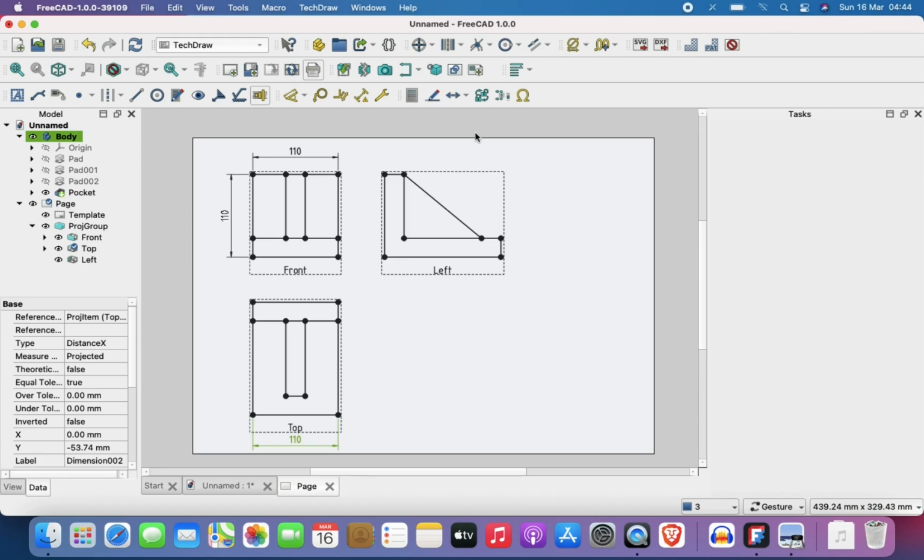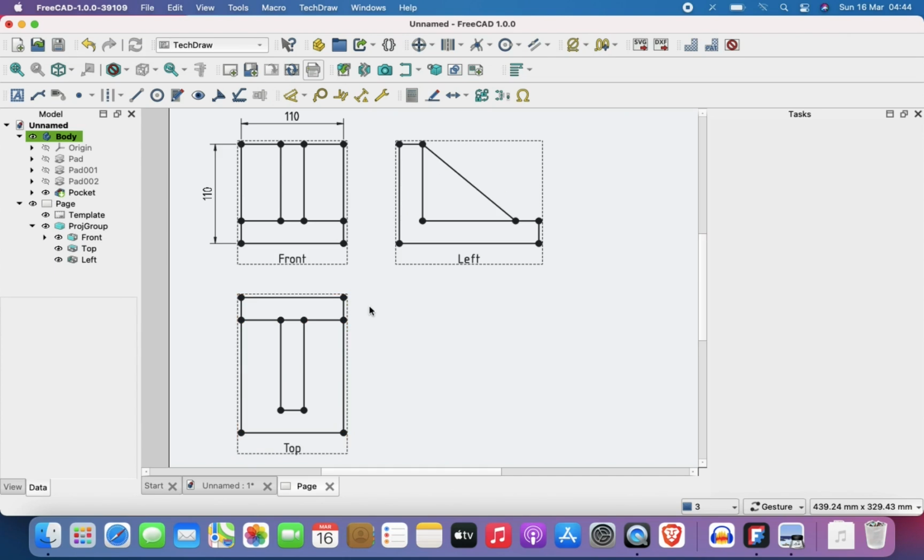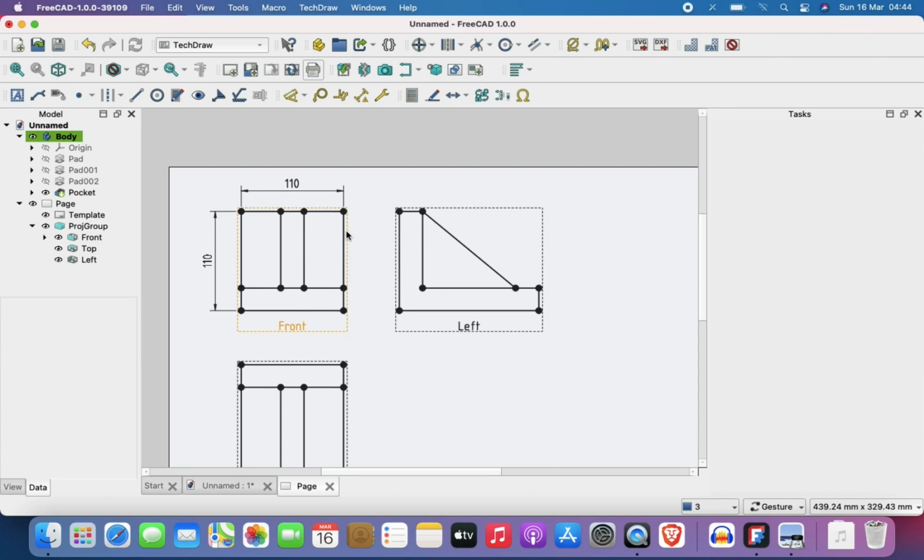And sometimes those mistakes can actually happen in production, especially when you have made a technical drawing and you are asked to go and revise it. So you go and revise it and you change one, but you forget to change the other one. So we usually advise not to include redundant dimensions. For instance, this 110 is not appropriate. What you want to do is to fully dimension the part, giving it all the dimensions that are needed. So let's try to see if we can do that.